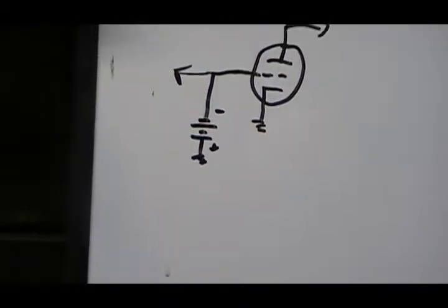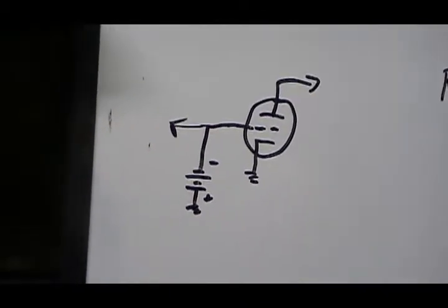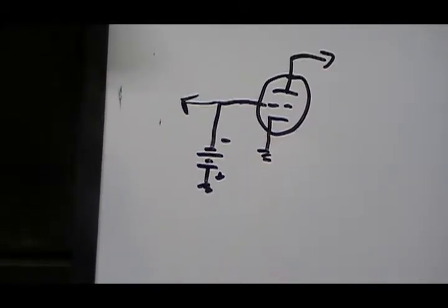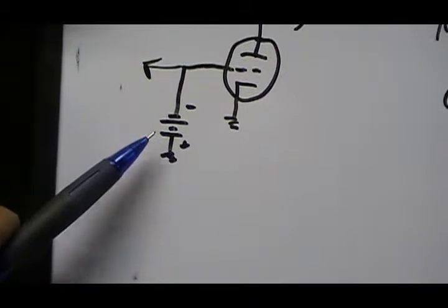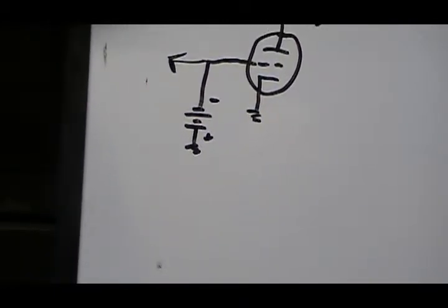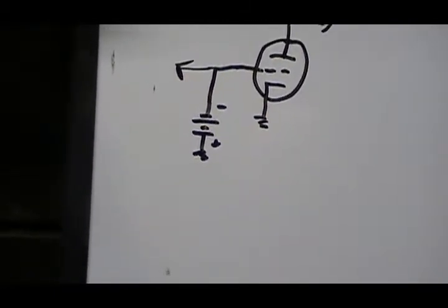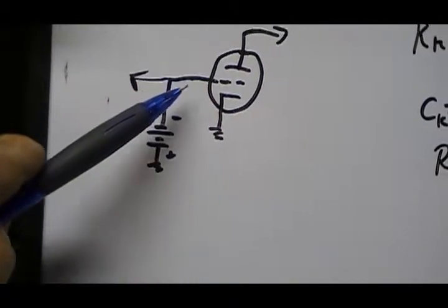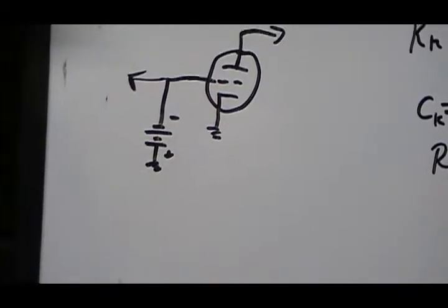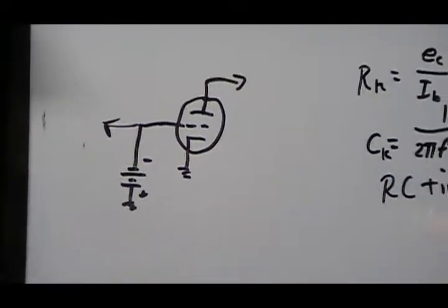You've got to realize, in order for that meter to work, in order to get anything to show up on that screen, it has to draw some current. So it's going to load these. These things were designed not really to put out much current at all. Very little, way down to microamps, because they're designed for biasing a tube whose grid has no current on it.